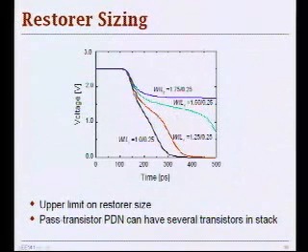This is pretty much an exponential decay, right? So that's we're discharging the caps. But what happens at this time? It hits VM. So if it hits VM, then your inverter switches. It turns off your restorer, and you can actually see faster discharge times here. And why is this approximately linear? This is approximately exponential, and why the change of shape here? What's happening here?